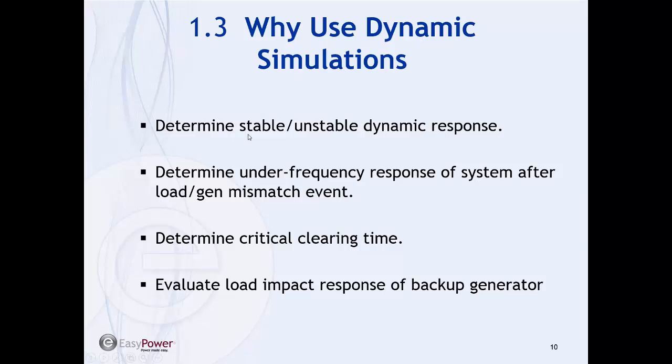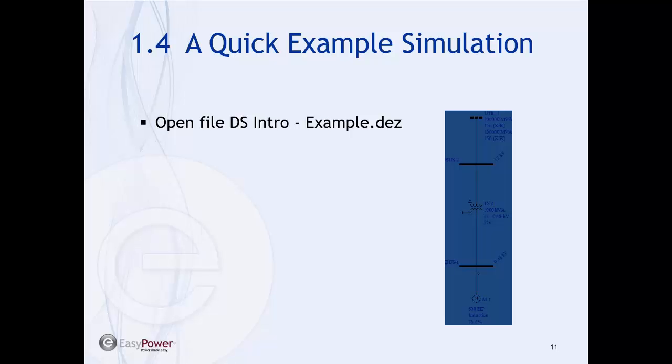We are able to determine the stable and unstable dynamic responses. We are able to determine the under frequency response of the system after a load generator mismatch event, determine critical clearing time, and evaluate the load impact response of a backup generator. And let's take a look at a quick example.